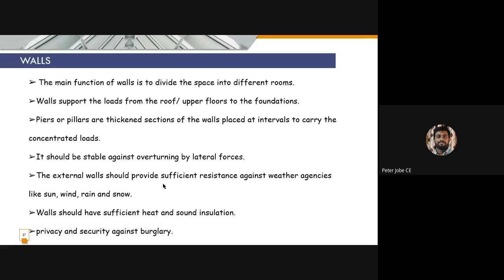So instead, if we are using columns or pillars, both the columns and our roof slab might be concrete. So the reaction of these two elements, we can interconnect using steel bars, and the reaction of these two parts will be almost similar. And since we have also provided steel bars inside, it may not cause as much damage as a load-bearing wall can cause in a small building. In many cases, you might have noticed that whenever an earthquake happens, it's always safe in a very large building, and the major casualty will happen to people who are living in small buildings. What is the reason?